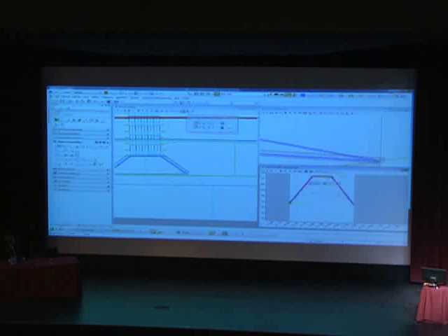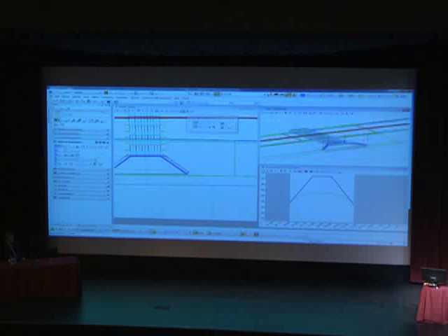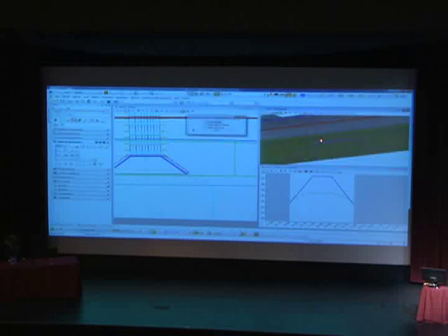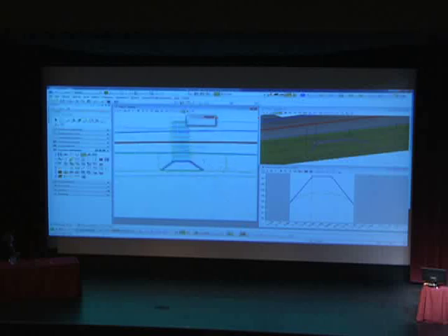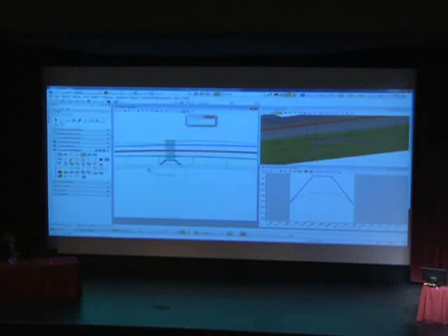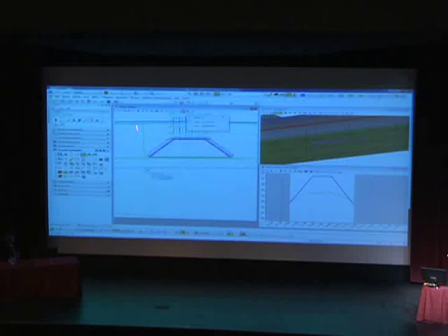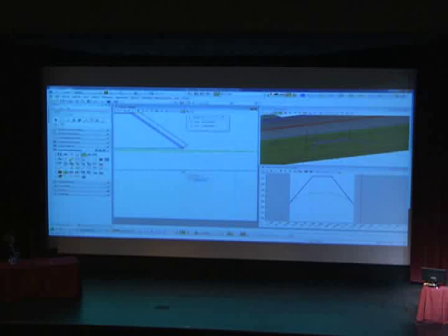Why is that? Well, one, I have to reprocess the corridor. Two, I probably have to change the template drop that's on there. And three, that line that I just drew is not a corridor reference to my template. All right, and then there's another one. What I want to show you here is that it's not connecting. The way these templates work is they're placed every so many feet. You say 10 feet, 20 feet, whatever it may be. But what I want to show you is that these green lines here each represent a separate template drop, and then the software interpolates between those two templates.